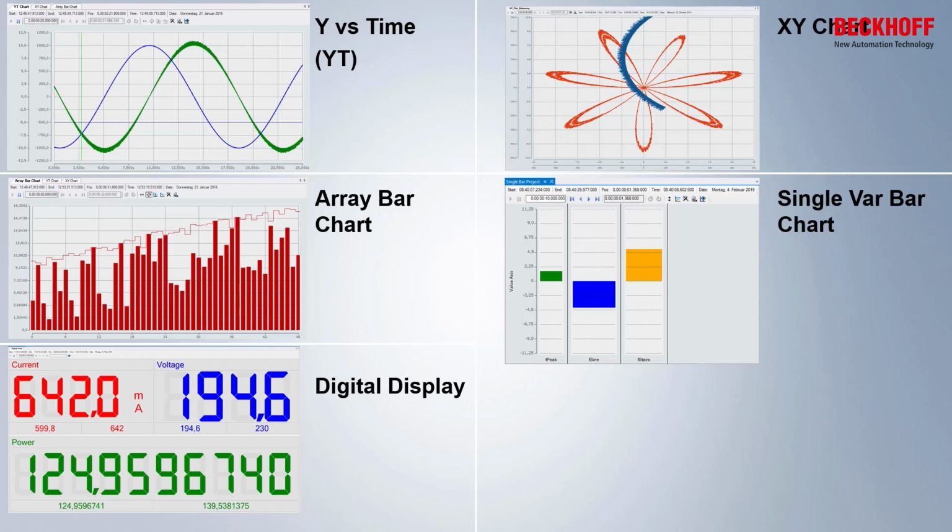And those things can be correlated to what was the motion controller's position when I gave the position out via EIP to some sort of device. I can correlate these and say, okay, what was the timing difference between those two commands, for example? And for that, we would use a Y versus T or a Y versus time chart, as we see in the upper left-hand corner here. And there's various different charts for different applications. So I gave you one for the Y versus T.